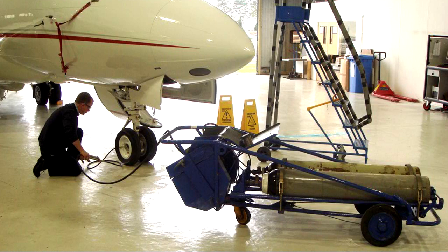Tyres in use must be kept inflated to the correct pressure, using nitrogen or another inert gas with less than 5% oxygen content, as underinflated tyres may move or creep around the wheel, and overinflated tyres will cause other types of failure. It is estimated that 90% of all tyre failures can be attributed to incorrect gas pressure.